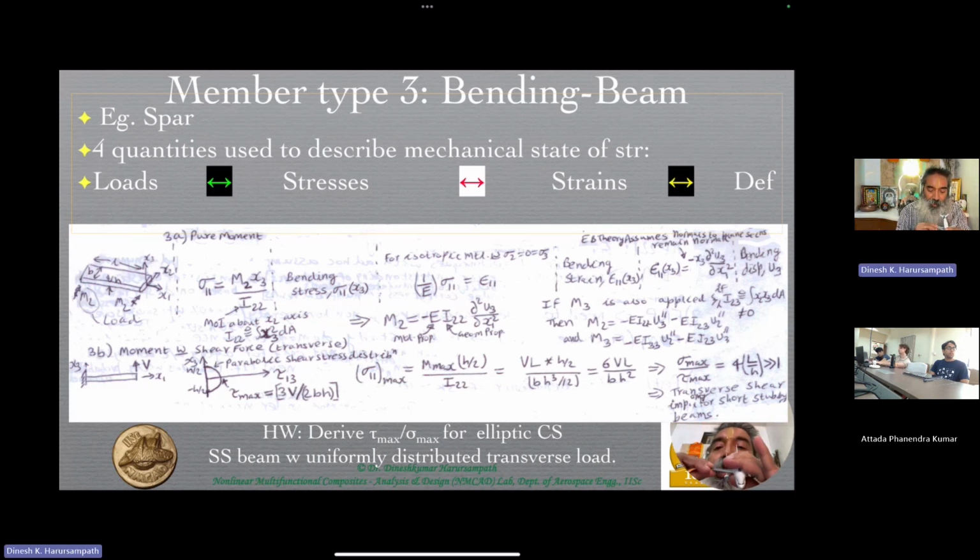And when it is bending upwards, even though at any given cross section the normal stresses are in the 1 direction and the strains are also along the same direction, the major deformation or displacement that is taking place is in the x3 direction. As we've been repeatedly telling under many different contexts, the wingtip can move by the order of a few meters, and that's essentially in the x3 direction, along the thickness direction, not along the chord or the span.